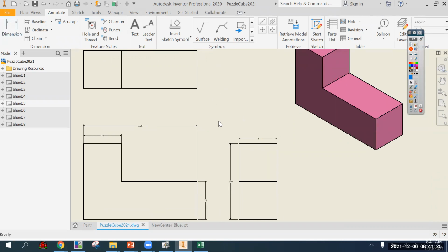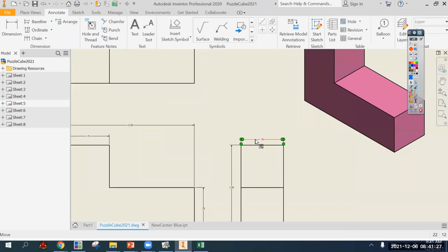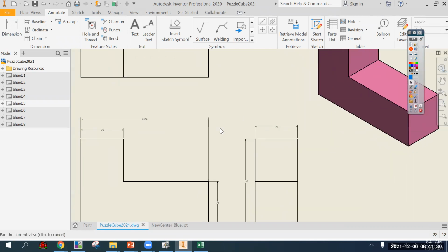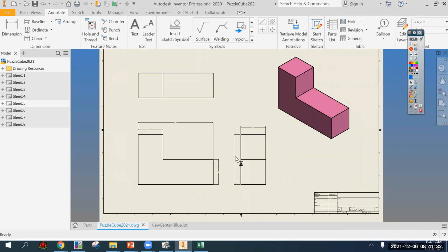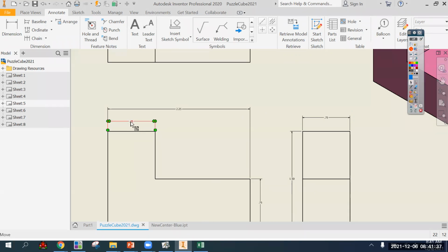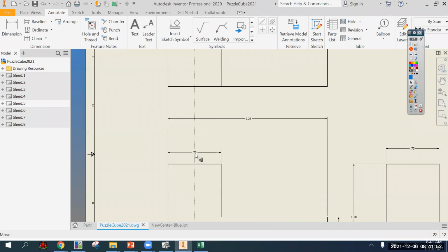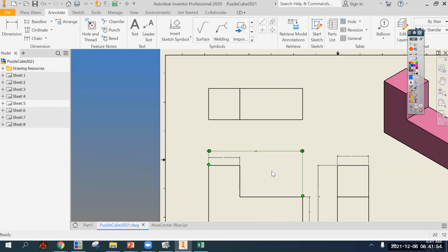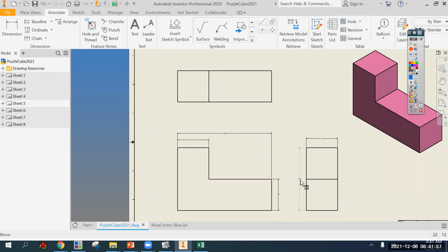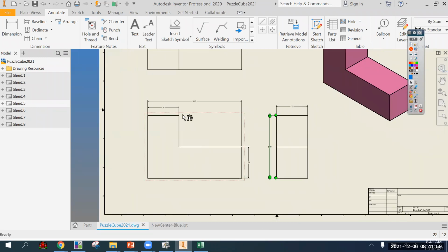But having both is wrong. Having both is over-dimensioning. And I'm just going to put it over here on the right side view because I already have another dimension on the right side view, although that's just completely arbitrary. And tidy things up, you like having one long dimension like that and another one like, I don't know, that sort of looks sloppy. I wouldn't ever take points off because you had it like this instead of like this. But be consistent, make it look nice and neat.